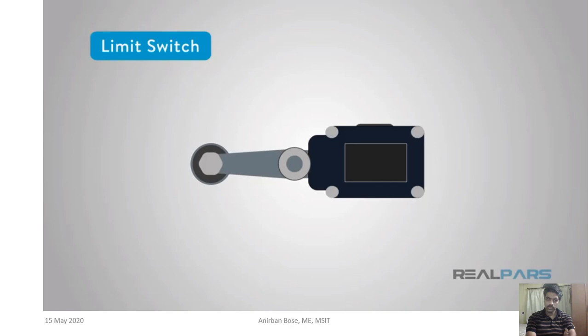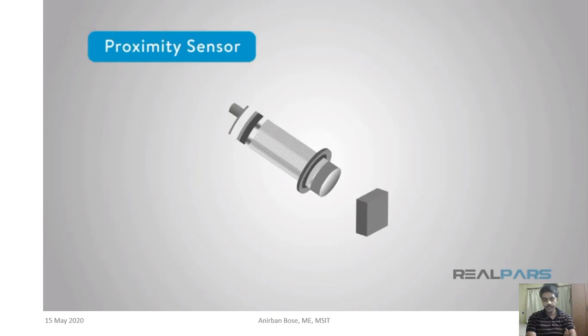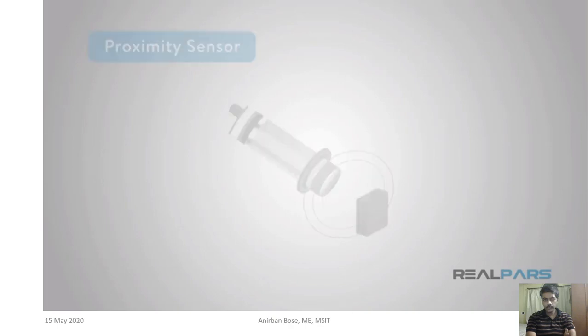Limit switches are still used in ugly, dirty environments thanks to their armor-plated construction. One big reason they have become less popular over the years is that they're huge compared to many of the other sensors available. Proximity sensors, very often called proxies, are used for detecting close metal objects using magnetic fields. In many environments, these have replaced limit switches in position sensing applications.